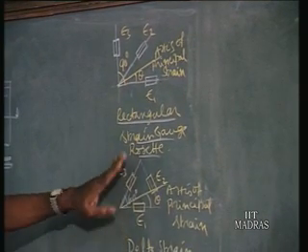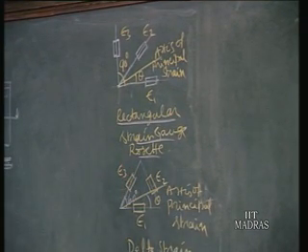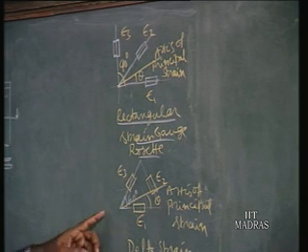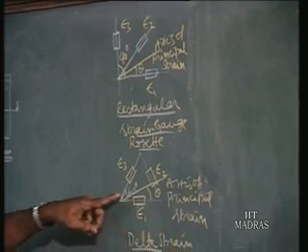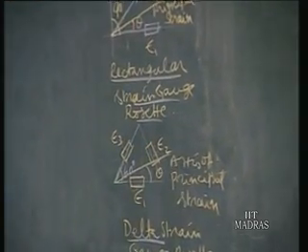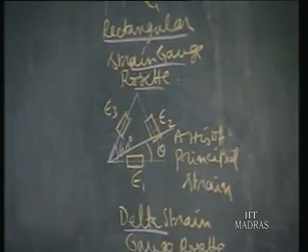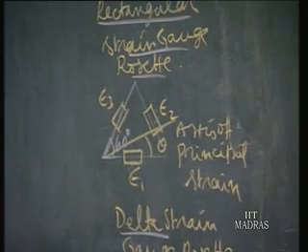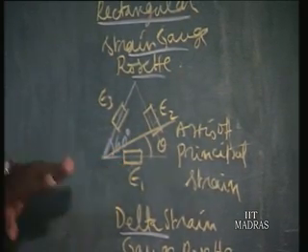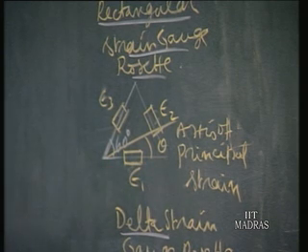Measuring each strain, you can then find the principal strain. The formula can be referred to in standard textbooks. By measuring the three strains, the principal strain and the axis of principal strain can be computed in terms of epsilon 1, epsilon 2, epsilon 3. That is, in case you do not know the strain or stress direction, you have to go for three strain gauges fixed on the structure, and from there we can find out the maximum strain produced in the structure where we have fixed the strain gauge.